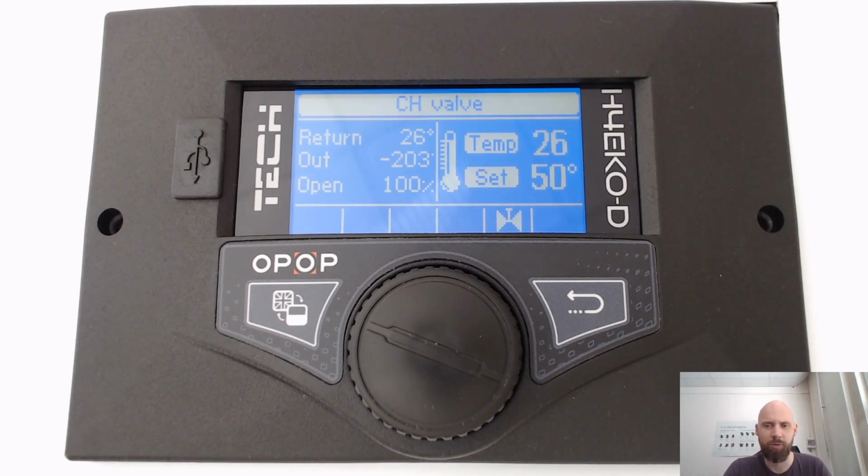And with our control unit, there is a valve or valve pump, which is named additional pump. Additional pump is a third pump we have inside the control unit. First is pump for central heating. Second pump is for the hot water production, and third pump is additional pump which can be configured. So basically, you can select the way of the operation of the pump.